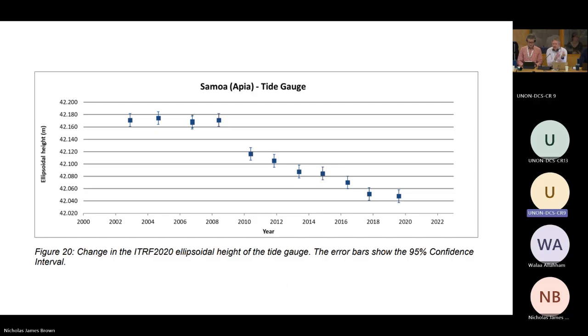So that combined with leveling, we have found we can get millimeter accurate results. Whereas if you have a GNSS station mounted on a tide gauge, you can get more movement from the platform, as we heard. You can also get more multipath effects from the ocean. So we're worried that we're going to degrade the GNSS signal. It would still work, but you can't do it as accurately as if you have a station on the land embedded into bedrock. But great point.